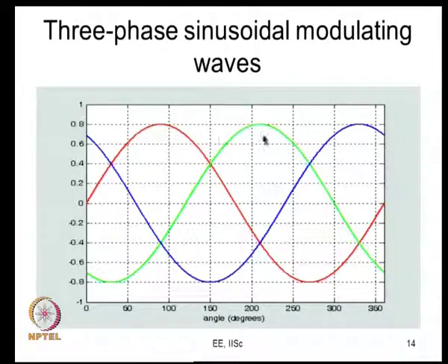So, there are 3 sinusoidal signals R, Y and B. The Y phase is represented by a green signal instead, just so it is easier to see. I have given 3 identical modulating signals, and you would compare them with the high frequency triangular carrier and produce the PWM signals. The comparison of the R, Y and B phases with the carrier gives PWM signals which switch the R, Y and B phase legs, as we know very well. And so, the inverter is running.